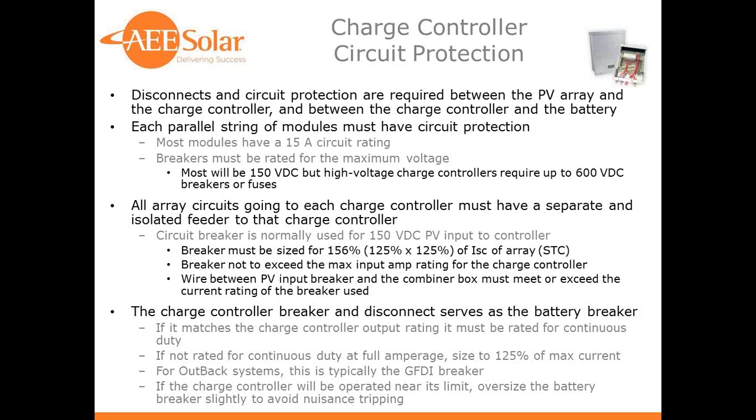The charge controller is considered a non-permanent device. It's a serviceable appliance. You need to be able to turn off all sources of power to that charge controller in order to service it. So you need to be able to turn off the PV array input and also the battery connection, in order to have the controller not have a source of energy that could cause a shock if you're servicing it.